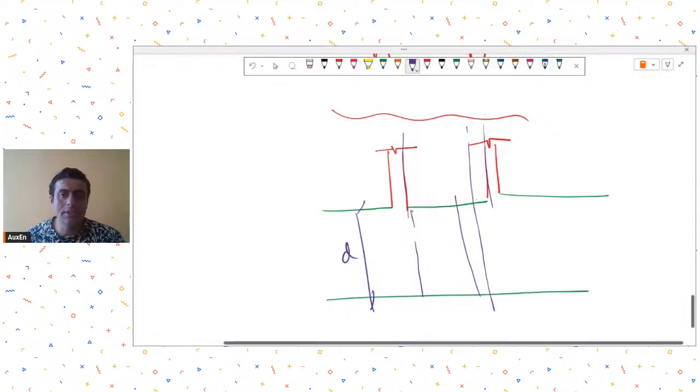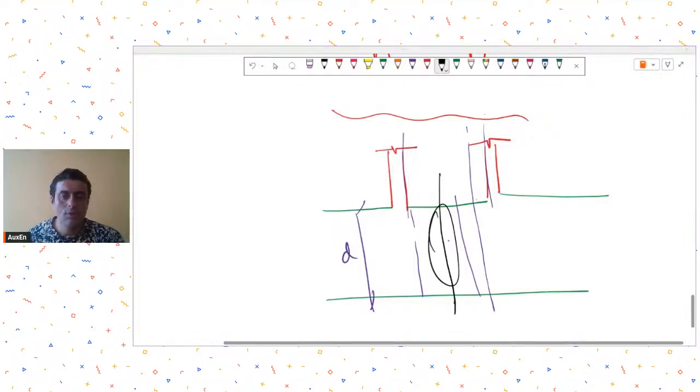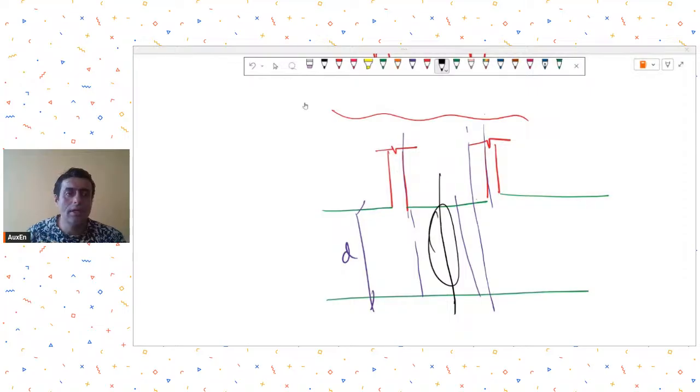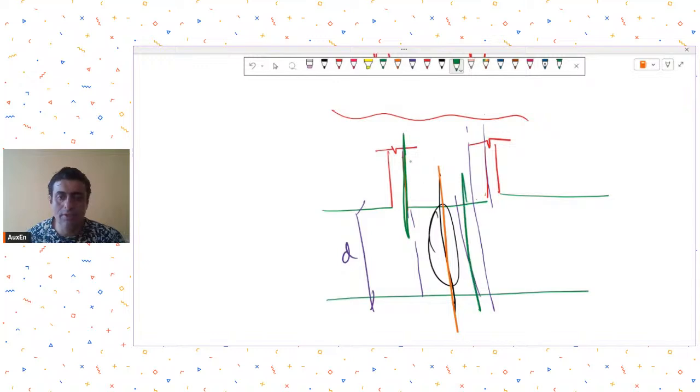The simple concept that you can use is that you find out the shear at these locations first, and then use, as you have rightly pointed out, the enhanced shear concept. Because this section is within the d distance, for this column the d distance section was here, and for this column the d distance section was here.